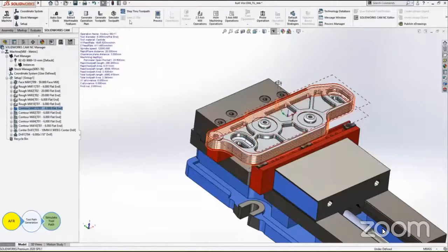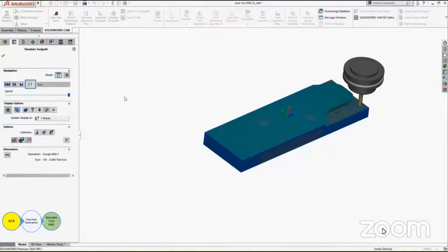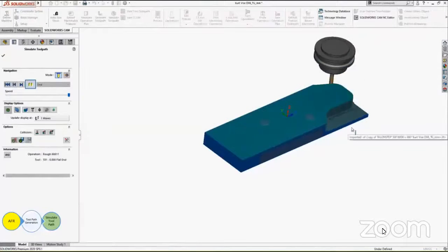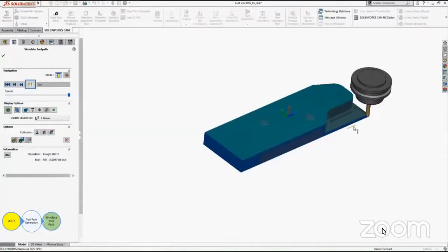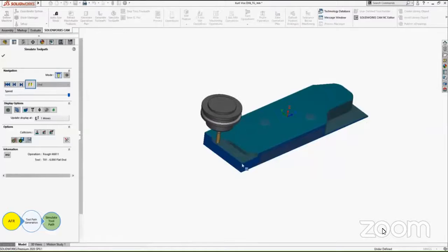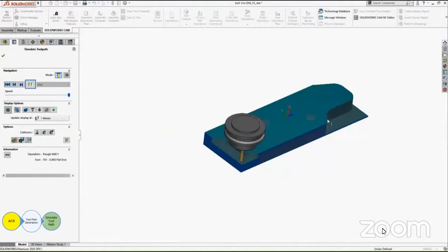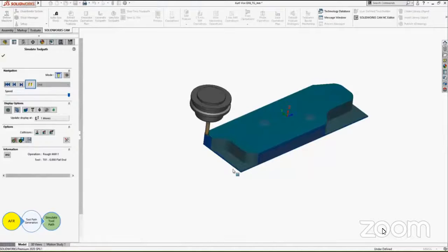So we have also generated the tool path for the rough mill. Now we will perform the simulation and see the result. Since we specified the end condition of the perimeter, it must leave some material at the bottom, which will be used for holding that stock material. So far, everything is going fine as we require.